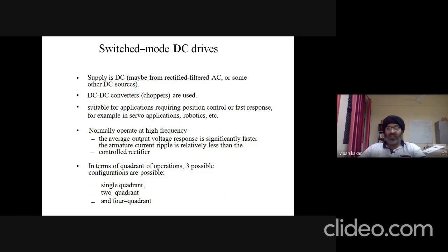While designing a DC to DC converter, we can select the values of all these parameters: inductance, capacitance, maximum value of coil current, minimum value of coil current, and the switching frequency, of course. Just by optimally deciding these values, we can easily get less than 1% ripple.